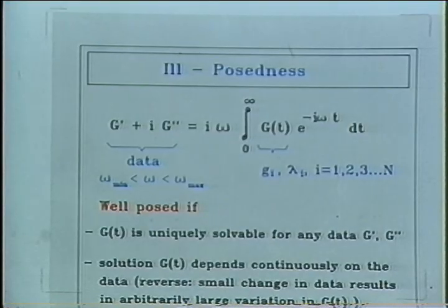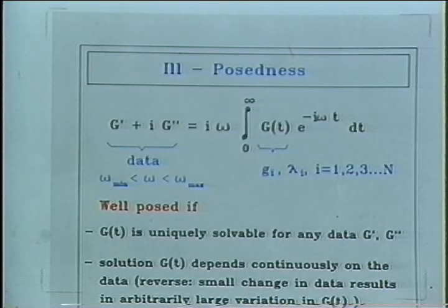So by using the Parsimonious model, the spectrum with the fewest possible relaxation modes, we are avoiding this problem of ill-posedness without following up why this happens. I guess it happens because we don't try to model the noise of the data. We stop putting in more and more modes at the point where we start jumping around with the noise in the data, and that would make the problem, of course, ill-posed. We are avoiding this in the Parsimonious model.